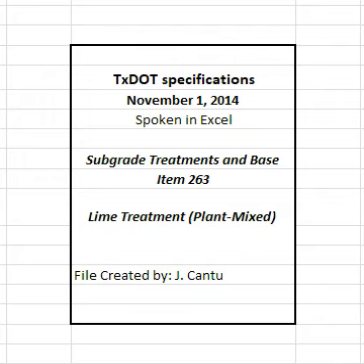Rework, recompact, and refinish material that fails to meet or that loses required moisture, density, stability, or finish before the next course is placed or the project is accepted. Continue work until specification requirements are met. Rework in accordance with Section 263.4.4, reworking a section. Perform the work at no additional expense to the department.